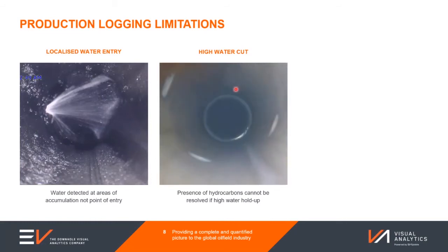And you can clearly see the hydrocarbon on the high side of the well on the video. And in fact, we chase it down to this sliding sleeve, and that's the final point at which we can see oil inside the well. So we understand immediately where that oil is emanating from, and that underneath that, there is no further hydrocarbon contribution. But again, with such a small volume of oil situated at a remote part of the wellbore, that would be incredibly difficult for even array production logging sensors to sample, either through spatial placement of the sensors or the physical location of the sensors and how they're deployed.